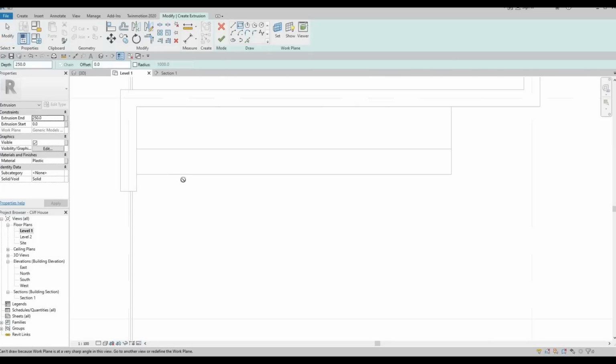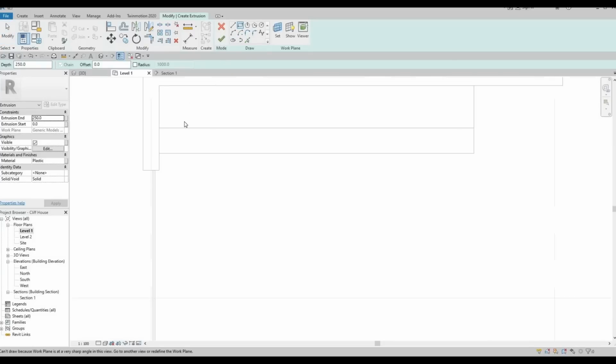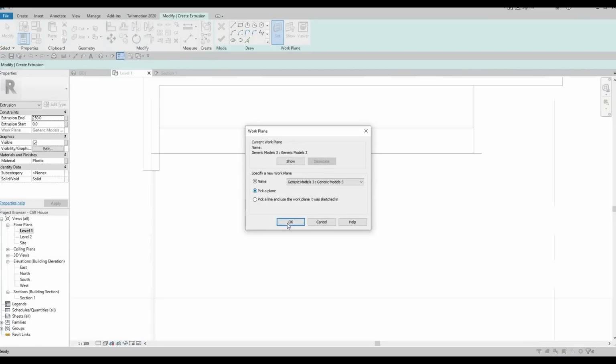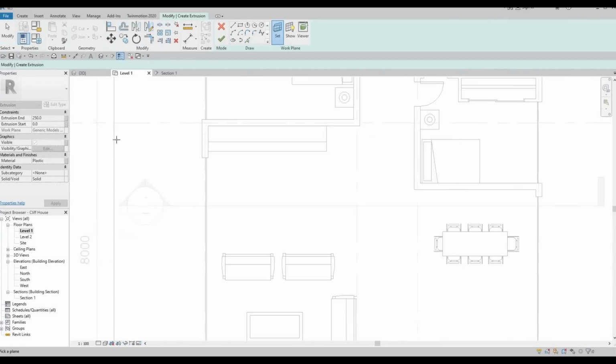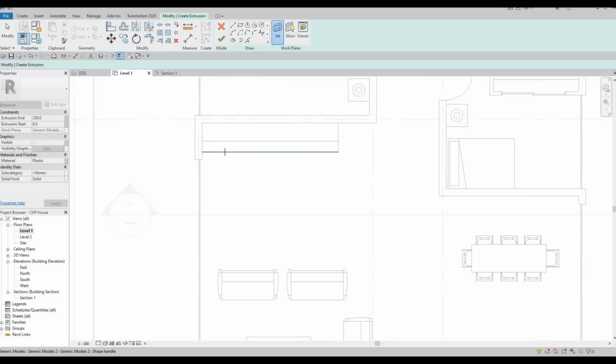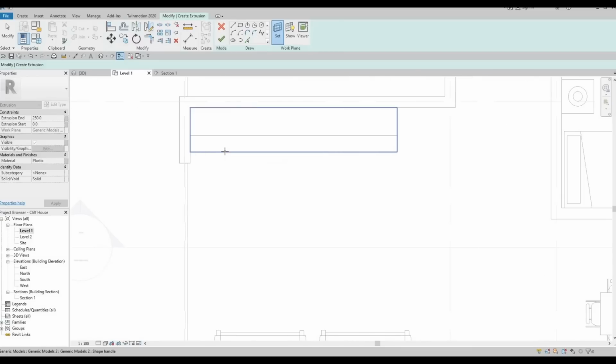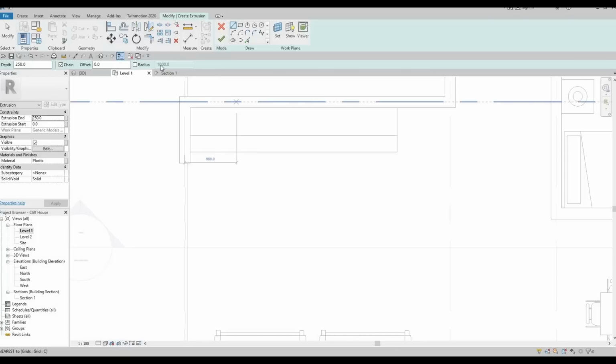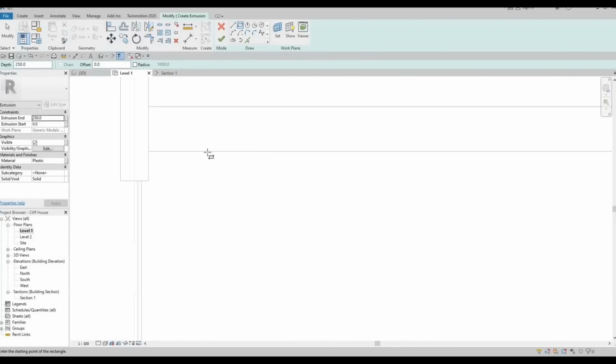and let's try, actually I set this one differently. So I'm gonna click on set again, pick a plane, and I want this plane to be the same plane as the top. And then after that, we just need to create a simple handle like so.